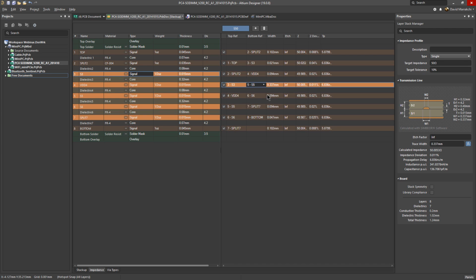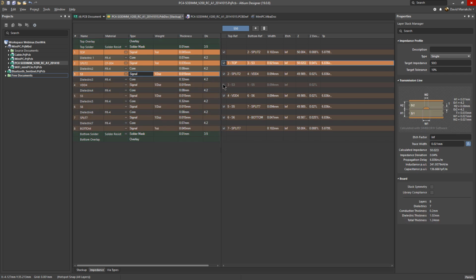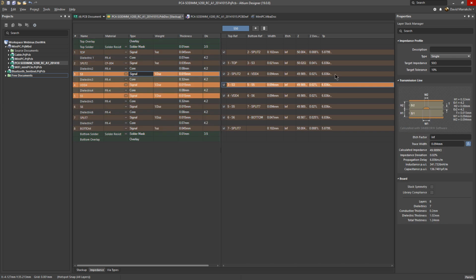And you can include or exclude any layers from that particular profile. For this particular one, we'll just keep all of them, and this is a 50 ohm impedance setup. But what value do you set? Well, in general, what is important is that the impedance, whatever you choose, is controlled along the entire length of the line. And most designs will have some sort of constraint that would often dictate the impedance, such as 65 ohms for PCI. And typically the value will range between 45 ohms and 90 ohms. So we'll keep it at 50 ohms.